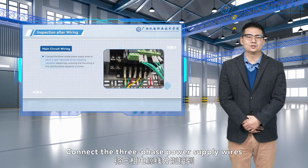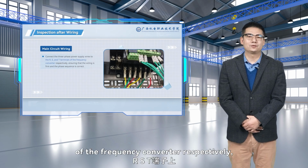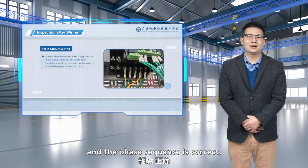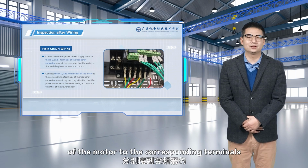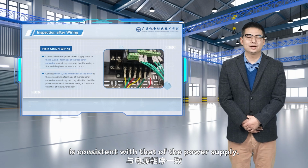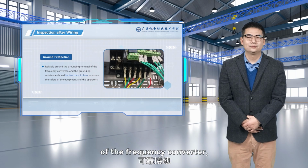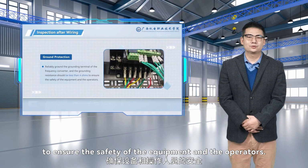Main circuit wiring. Connect the 3-phase power supply wires to the R, S, and T terminals of the frequency converter respectively, ensuring that the wiring is firm and the phase sequence is correct. Connect the U, V, and W terminals of the motor to the corresponding terminals of the frequency converter respectively, and pay attention that the phase sequence of motor wiring is consistent with that of the power supply. Ground protection. Reliably ground the grounding terminal of the frequency converter, and the grounding resistance should be less than 4 ohms to ensure the safety of the equipment and the operators.